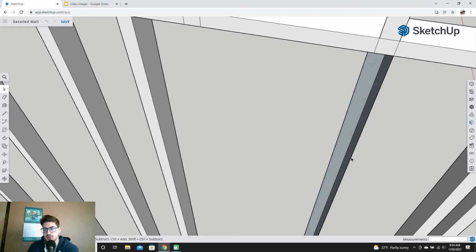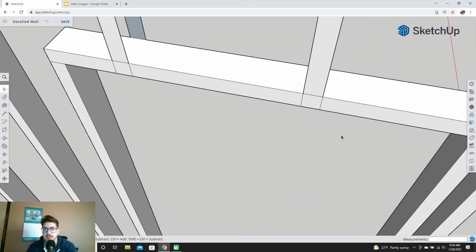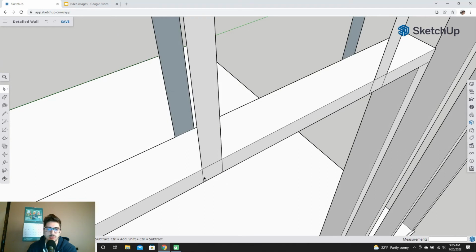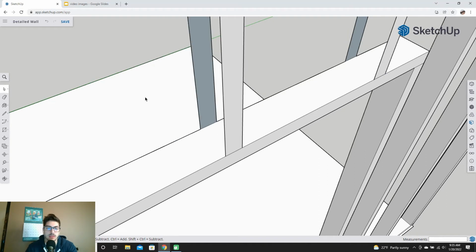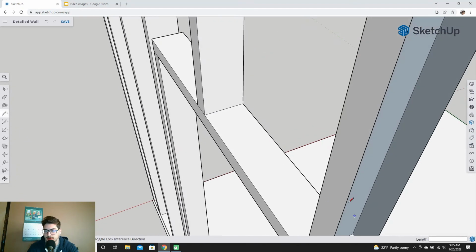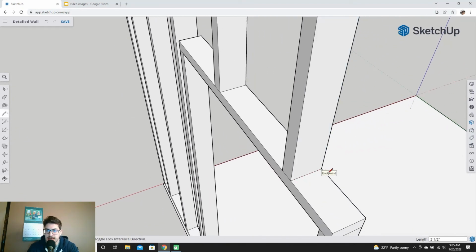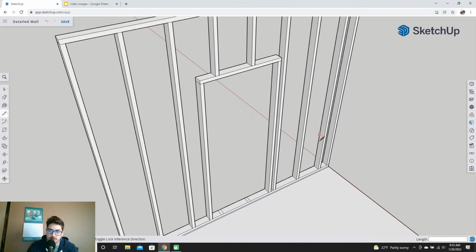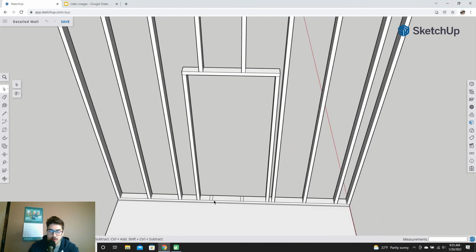So just clear out everything you had made that's now inside the doorway, and delete out these extra lines in your header beam. Delete, delete, delete, delete. I'm not going to say delete every time. Okay, and the last couple things you should draw in, because you notice your verticals got cut off here so they don't look like 2x4s anymore. Go ahead and draw in the feet. I don't know if feet's the right term. Go ahead and draw in these bottom lines so that they'll fill in. But I'm going to zoom back real quick, so I'll clean up these lines as well.